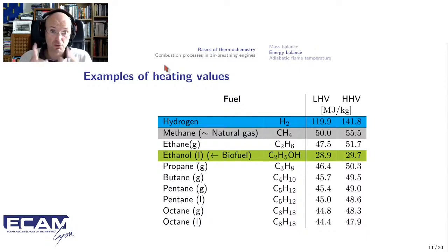The only exception, and it's quite clear in this table, is hydrogen. Hydrogen will release a lot of energy. But at the same time, keep in mind that hydrogen is really not dense. It's a really dilute gas. It's really complicated to have a large amount of hydrogen in the same volume. So if you want to produce the same amount of heat for the same combustion, replacing, for example, hydrocarbon by hydrogen, you will need to increase the pressure in the hydrogen tank a lot. And so the heat released when divided not by the mass but by the volume is really not so favorable to hydrogen.